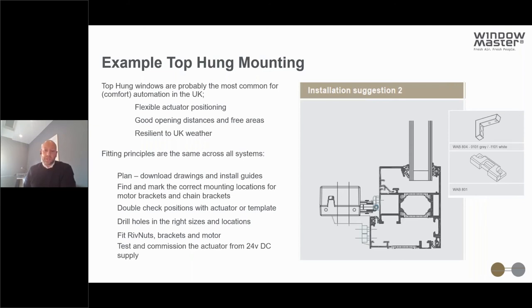Our actuators, because they have to fit different windows with different distances in the closed position, you go through a short commissioning process of opening and closing the actuator, and that helps it to find its home position and sets that at the initial commissioning.